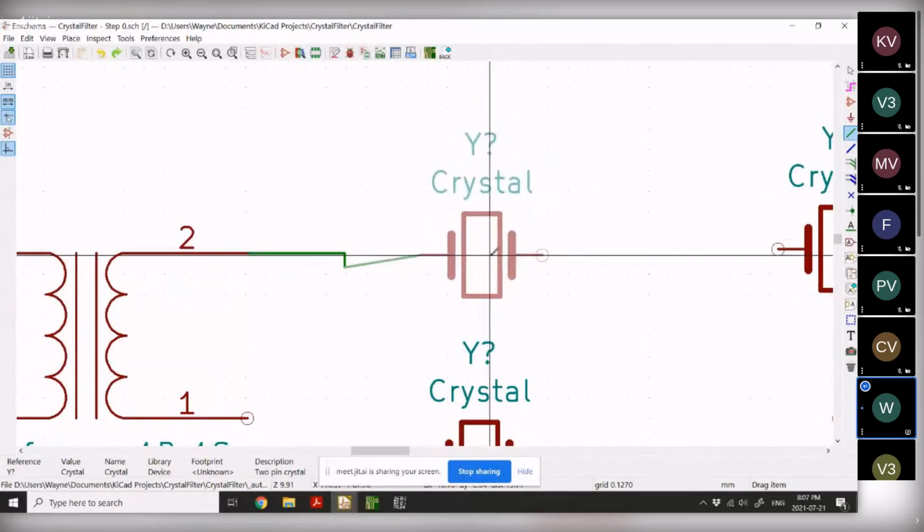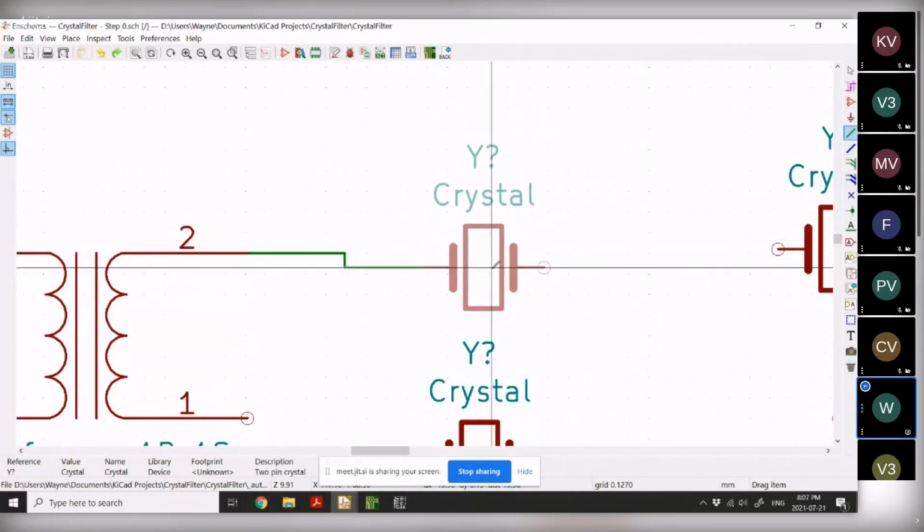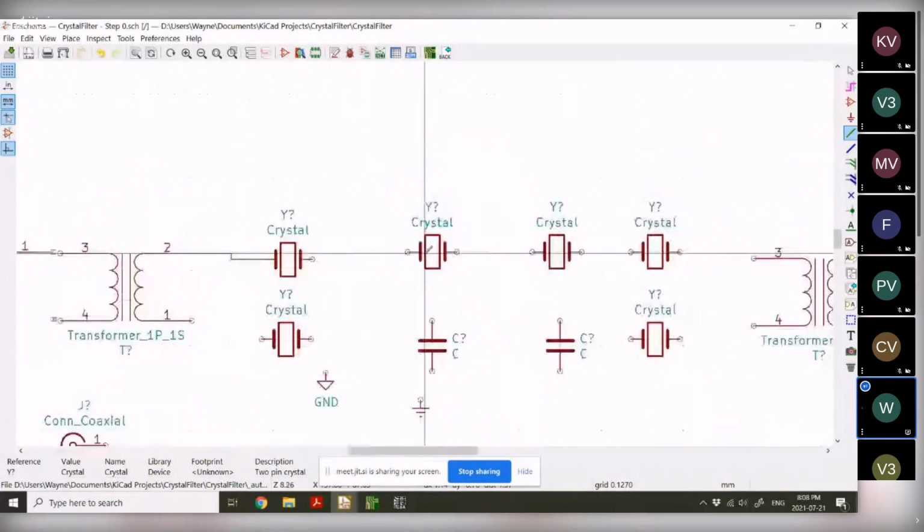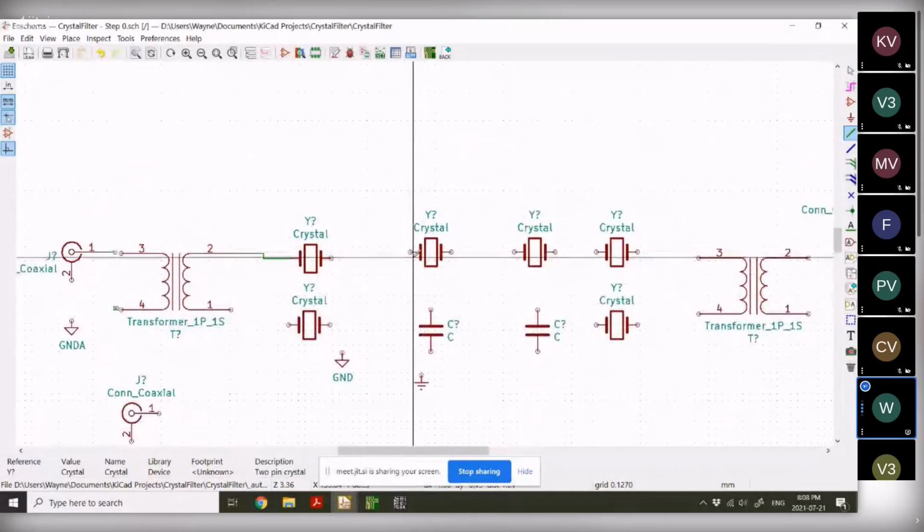So if you're trying to get these things lined up, line them up first, then draw the lines, or you'll be deleting segments of lines. Okay? So what you want to do is have your diagram lined up the way you want by placing all of the components before you do any wires. And I think maybe it doesn't matter in LT Spice, but it never troubled me as much, I guess. All right? What else can I show you before I move to the next stage?